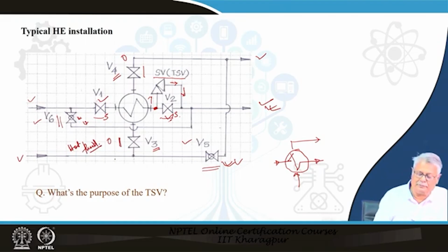possibly a hot liquid, the liquid which is cooped up between these two valves will get heated and it will expand. The expansion of liquid is always much larger compared to the metals. So, you will have an overpressure here, or the pressure inside will keep on increasing. In order to release this pressure so that it does not damage your equipment mechanically, this safety valve allows a passage of the overpressure liquid and reduces the pressure.